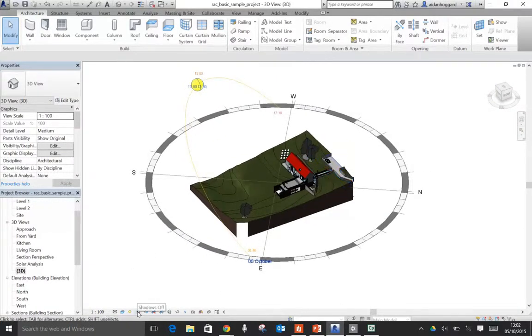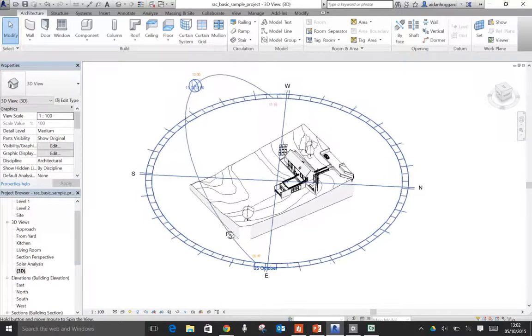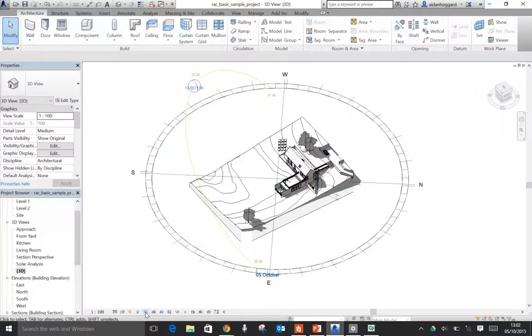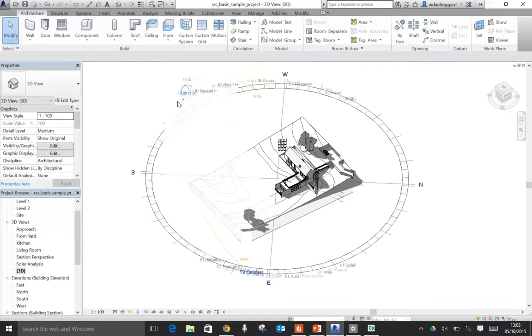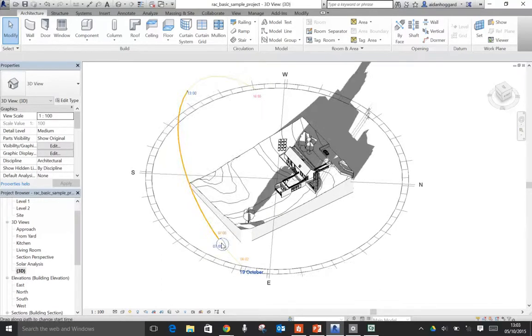And if we go to the next one, shadows, and put the shadows on, and I'll just change that back to a hidden line view. So I've put the shadows on using this button here. So shadows off, shadows on, pretty straightforward. I do cover this in more detail, but just to briefly show you, you can actually just pick up your sun and drag it. So you see I'm dragging that sun around and moving the shadows. Okay, but that is covered in another lecture.